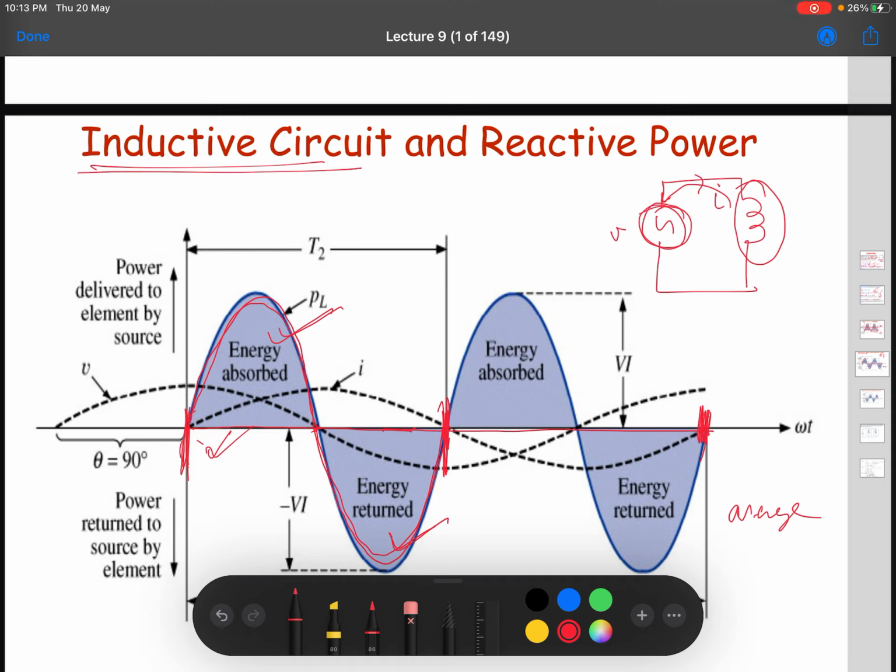That is what the concept of reactive power is. You don't find this coming out of the circuit, but according to this phasor multiplication, what we find is that this is there in the circuit, oscillating between the source and the inductor here, and the net power given out of the system is actually 0. So when you integrate this positive half cycle and negative half cycle over a cycle, you will find that the net power is 0. So no power goes outside of the circuit. So this is for reactive power. So in this case there is in fact no real power.